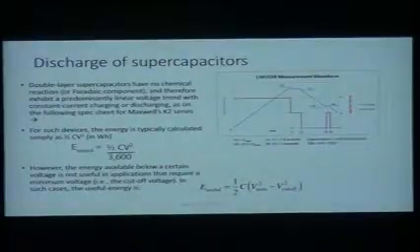Well, capacitors are not like that. Double-layer capacitors in particular, as they discharge at constant current, the voltage drops linearly. And so that's not as easy a thing to handle, and you have to kind of do more with your electronics in order to accommodate these changes. Same thing when it charges up. It charges in a linear fashion.